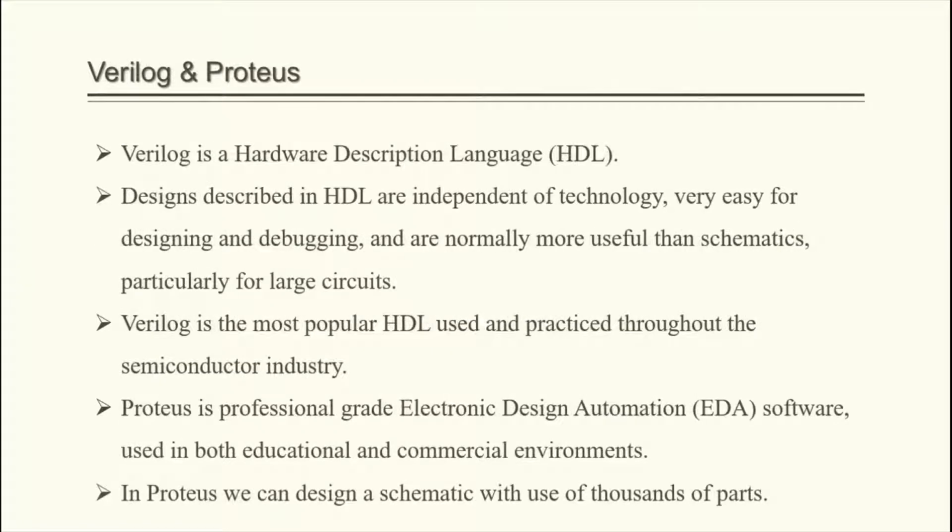And now if we talk about the software tools, Verilog and Proteus. Verilog is actually a hardware description language, HDL. HDL is actually some kind of language in which designs are very easy to implement and debug, and also normally very useful compared to schematics, especially for large and complicated circuits. So among these languages, Verilog is the most popular one used in the semiconductor industry.